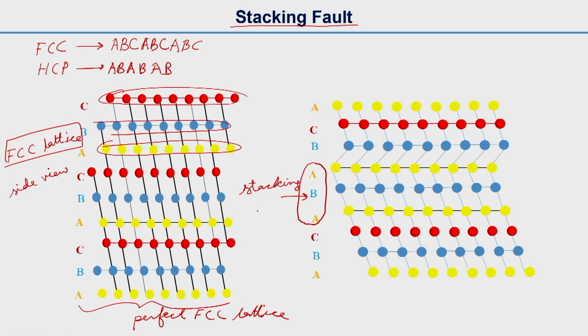So, in summary, a stacking fault is a fault in the stacking sequence of a crystalline material. You can check these basics from a materials science textbook. The stacking fault has a stacking fault energy, I will write as SFE, where E means energy. All the crystal defects, not only stacking faults but also dislocations, grain boundaries and twin boundaries, have energy associated with them. A perfect crystal may be at the minimum energy level, but these defects increase the energy. This stacking fault energy is related to mechanical twinning.